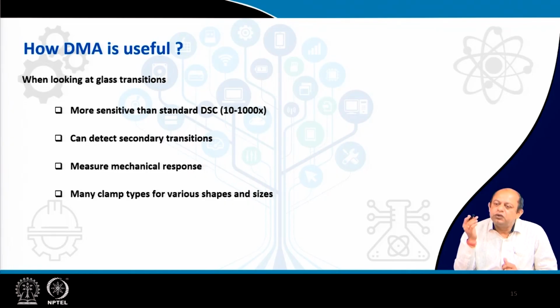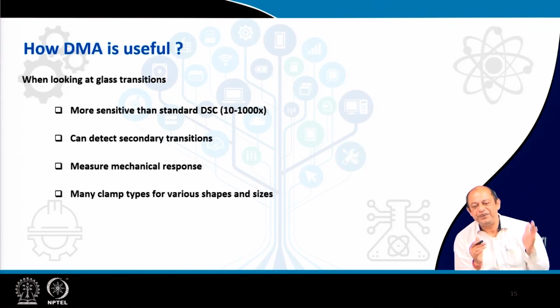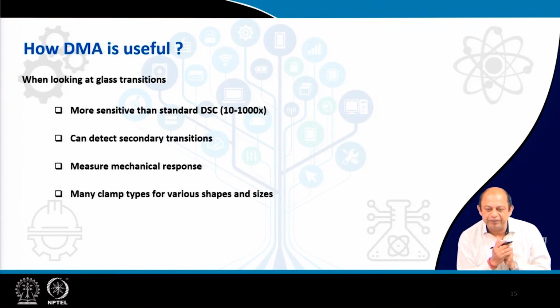So now, so far as glass transition is concerned, I said that it can be captured well from DSC. But in many cases, capturing many transitions, not only glass transition but beta, gamma and alpha transitions, is more sensitive than DSC, although I will not say it is absolute. Absolute determination of Tg is by dielectric experiments.